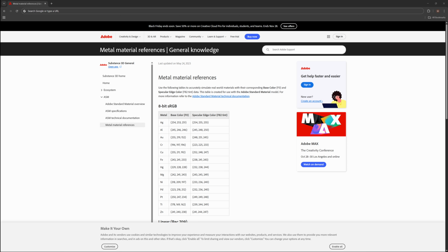So any color that the underlying surface has, or any tint that might be caused by a specific type of metal, won't be as properly described at a 90-degree angle. Because at that point, it's almost completely 100%. It's most likely leaning towards white and not tinted. So by defining it at the 82-degree angle, it contains a little bit more subtleties that the underlying material has. So you get a better and more accurate representation of overall what that material is doing on its reflection falloff. So that's something Unreal might eventually move towards.